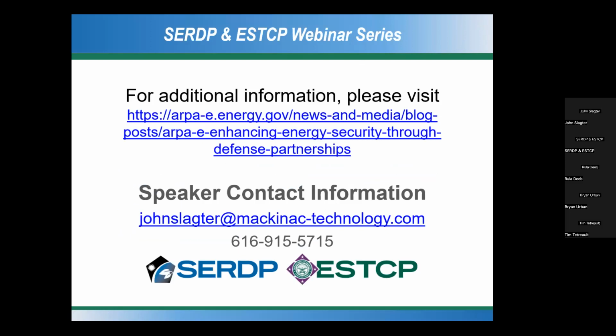Can the units that you described be used over operable windows that open and close? Yes. One advantage of the lighter weight material is that for casement windows that crank open, we can attach them right to the frame of that casement window without damaging the hardware, and they can open and close no problem. For other windows like double hung windows, we have hinged mechanisms that we can use to open the unit and then also open the window.